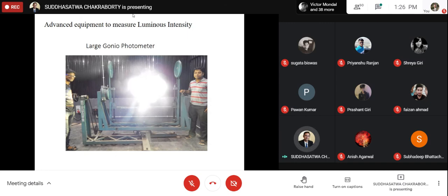to Illumination Lab, because already I've told you, we need to deal with basically theta as well as phi. That means we need to deal with a sphere rather than a circle. So in our measurement, we have plotted a circle because the vertical part we haven't considered. Only the horizontal angle we have varied. But in reality, once we are dealing with the biggest source, we need to measure the horizontal as well as vertical. So that's how the intensity data are plotted, as a 2D matrix, theta and phi.